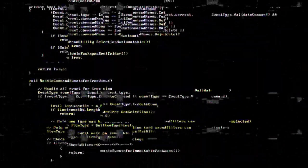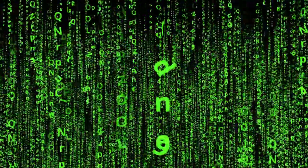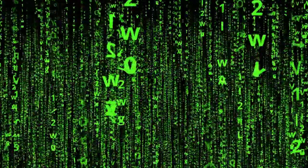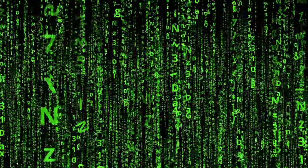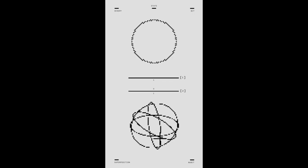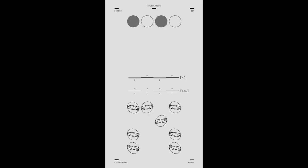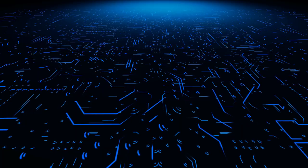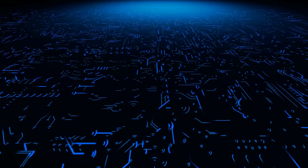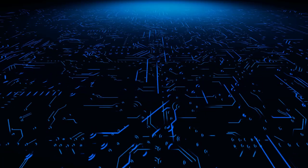The answer is transistors. A transistor is essentially an electronic switch. It can either allow electricity to flow or block it. By combining huge numbers of these switches together, engineers can build logic gates, tiny circuits that perform operations like addition, comparison, and decision making. Those gates combine into larger circuits called processors. The incredible part is just how many transistors exist inside a single chip. Modern CPUs can contain over 50 billion transistors, and all of them fit inside a chip about the size of a postage stamp.